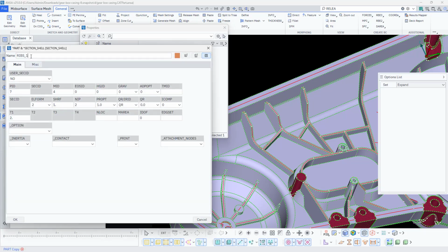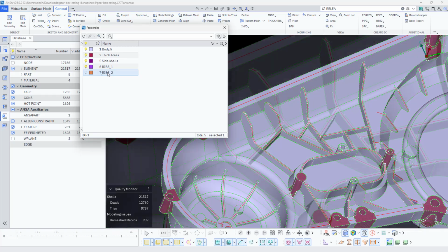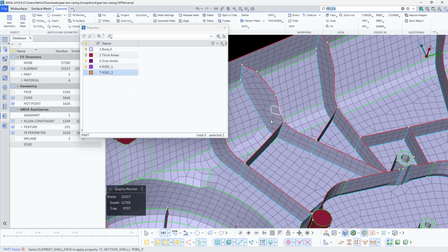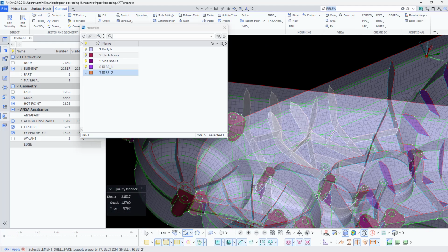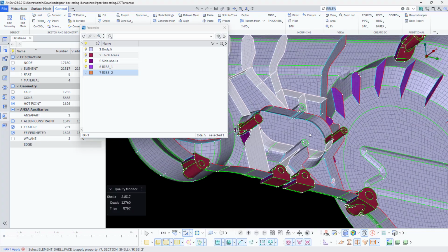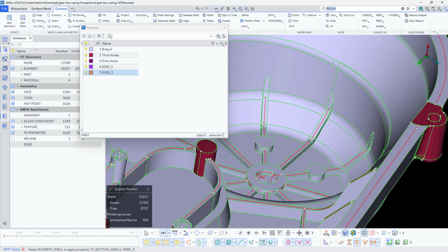Okay, I'll just rename it to 2, and thickness can assign 1.6, and then simply right click on this, and you could see the color codings also, right? So depending upon the PID, the colors will change. So here I'll activate the angle and I'll select all these ribs. So once you do that, you could see this is the preview. I'm just doing it by fast forwarding because it will take a lot of time to show you everything live.